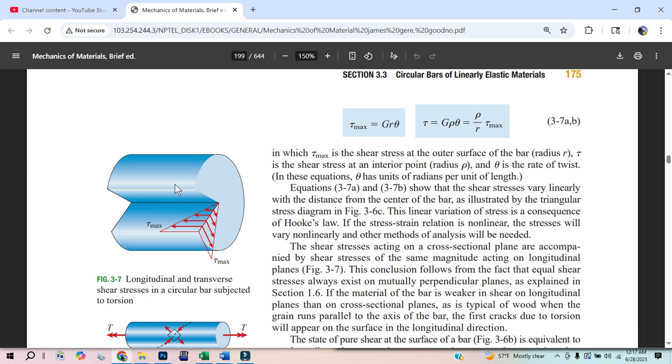I'm still taking this disk of molecules and shearing them up against that disk of molecules. I have a torque applied to this face. If I take a cross-sectional cut between there, and I take this chunk aside, that cross-sectional face has to balance. So if I have a torque on this face this way, the inside face will have an opposite torque.